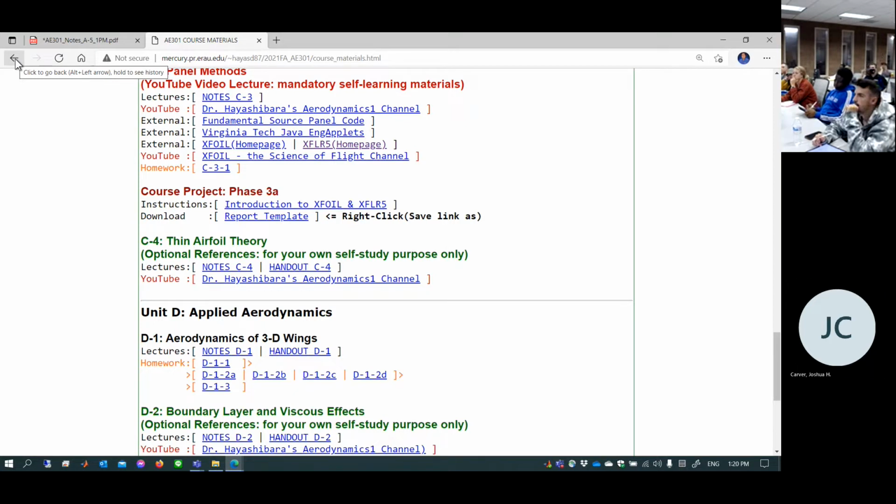Just a brief summary of how thin is thin? Like quarter inch? Okay. Thin airfoil means this is 100% academically analytical, completely ignoring the thickness. So you only talk about the camber line.